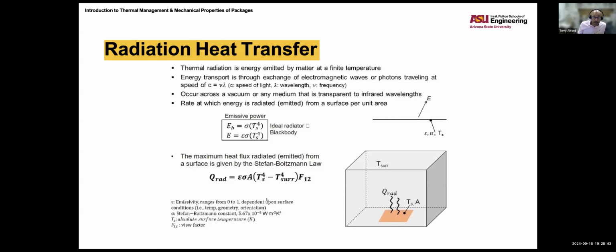Now, the drawbacks of it: it may not match the user's application because we're testing it, and there's a standard test condition we may not be using. And it cannot be used to verify component contamination, because we're looking at the entire package and measuring it. So we're not looking at individual components.